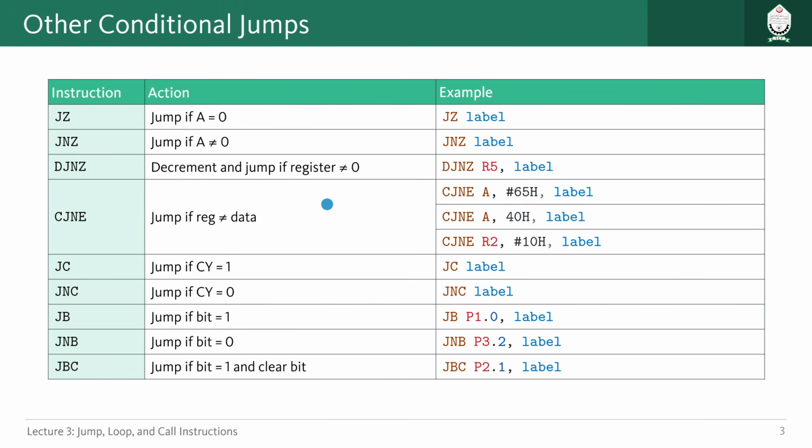Now, like here, we are just trying to perform one task, which is looping, in assembly language. This kind of instruction, called DJNZ, is actually a conditional jump. So we are jumping from one place to another based on our condition, whether that value is equal to 0 or not. Based on that we are jumping or not jumping. So these things are called